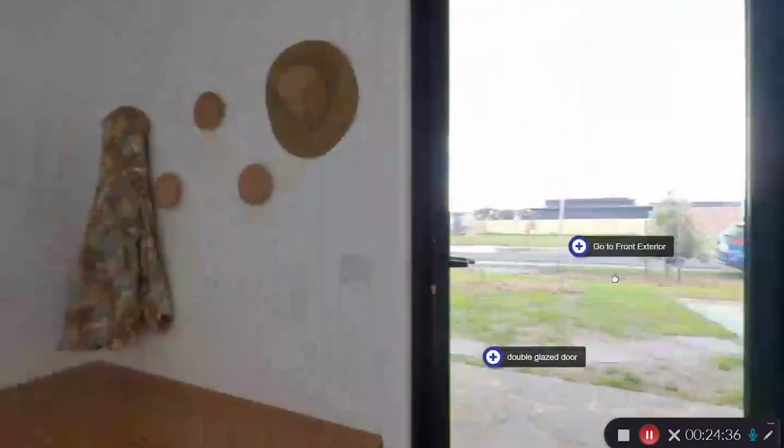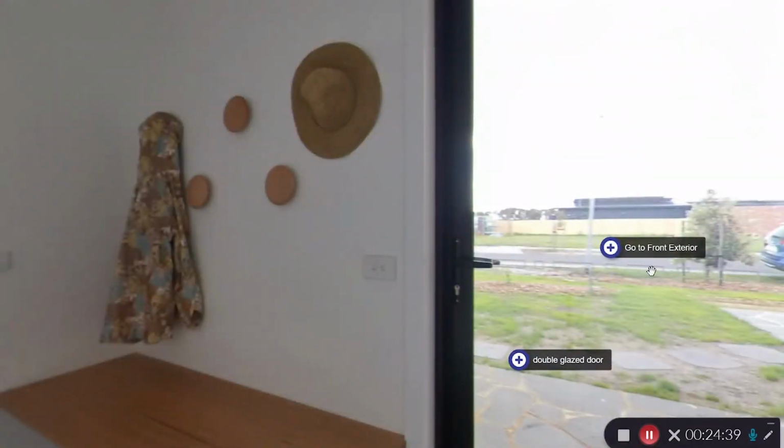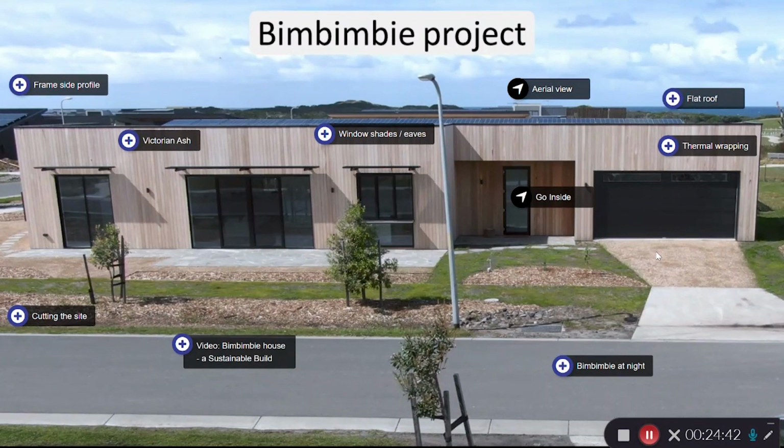And on reflection, I'll just go through the acronym quickly, which was materials. So MOTIVE. M for materials. Have we discussed materials? I think we covered several aspects of that in terms of how often we choose, what we should choose, being aware of what embodied energy we have, trying to recycle, being aware of transport, particularly if it's air transport of materials, and really looking for things which are renewable and affordable and as green as possible. And then not only which ones we choose, but where we put them. So for example, do we put things with high thermal mass in the sun, depending on our climate, or out of the sun.